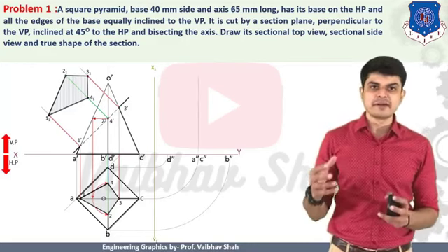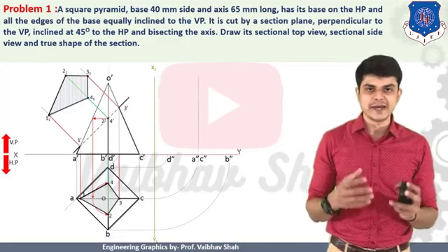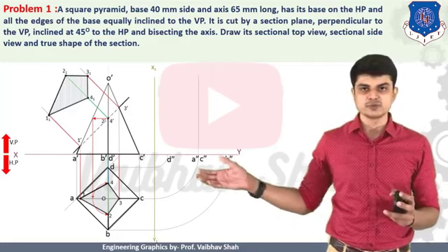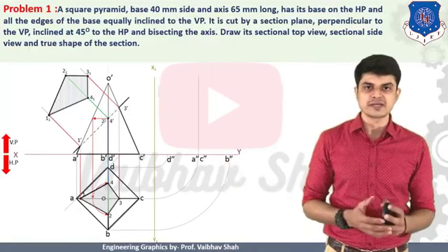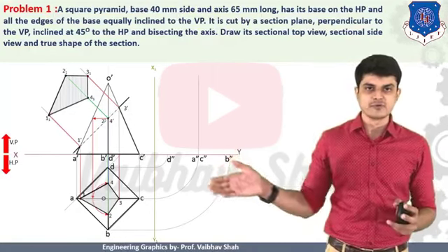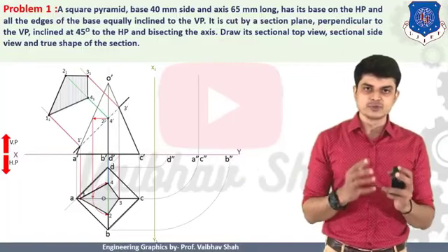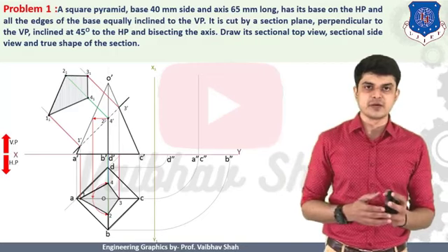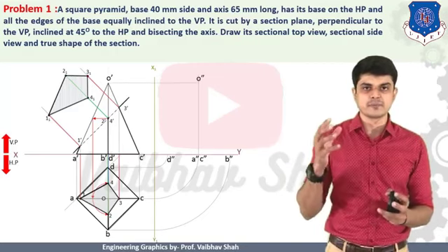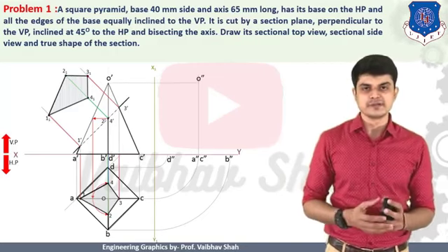After having all of the points generated on the xy line, we should finally transfer our fx point. You should transfer the fx point horizontally onto the x1 y1 line. Then after, you should revolve this like this, and then you should draw this line. After drawing this line, you should draw a straight line from your fx point O dash in order to get your point O double dash generated.